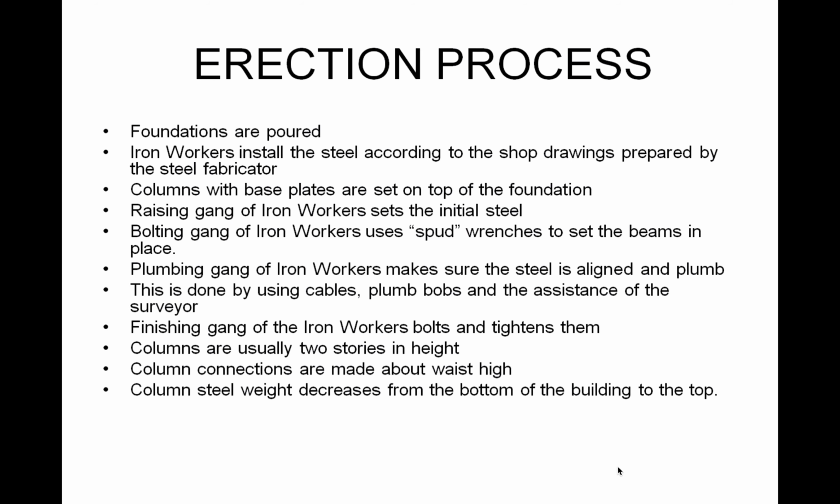And then, with tall buildings, generally the design will be that there's less steel as you get to the top, and that the members are smaller and lighter. Use the theory of like the Empire State Building, how you see it, the base is very robust. As you get higher and higher, you want less weight up there, more flexibility, and just less material, so you'll have smaller members, lighter members as you head towards the top.